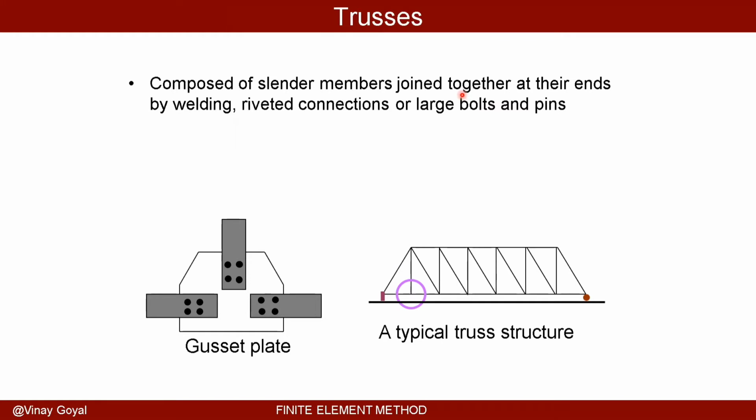And it is the kind of question you want to ask yourself. Can I make this modeling assumption? And yes, I agree with you. This seems like it should carry a moment. But when you look at the scale of things, you could conclude that perhaps this acts more like a pin, since it's so small compared to the scale of the rest of the structure. So I do understand that.